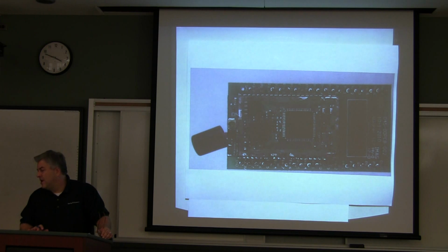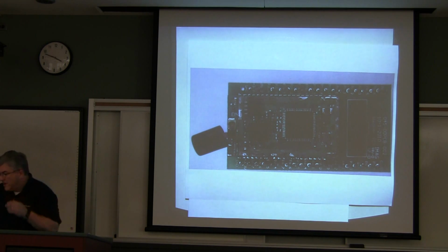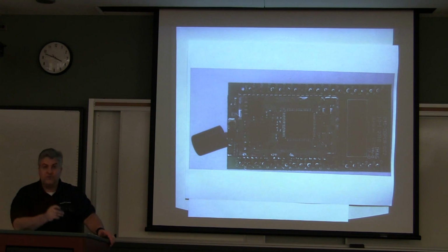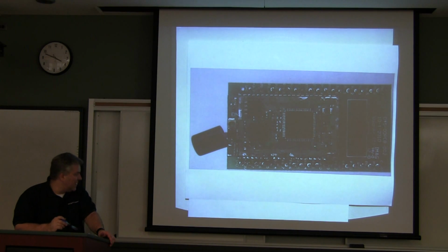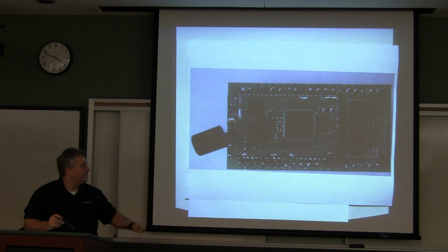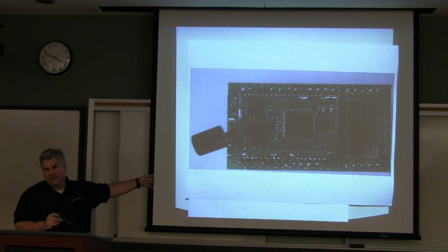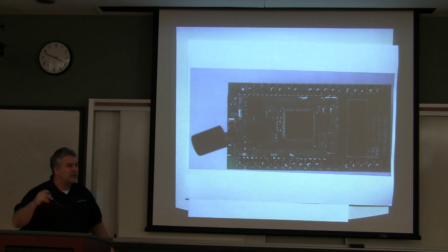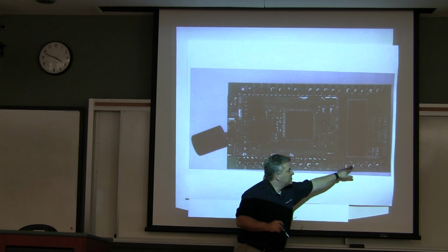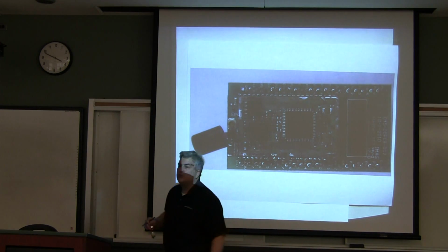So that's an example. We have a microcontroller that has lots and lots of pins. These are surface mount pins. The one thing about a typical manufactured device nowadays is that very little is through hole. In other words, see that green epoxy nylon type of device, there's very few things that actually go through. In this case, there are some up and down here. It's through-hole parts because it actually plugs into another module.